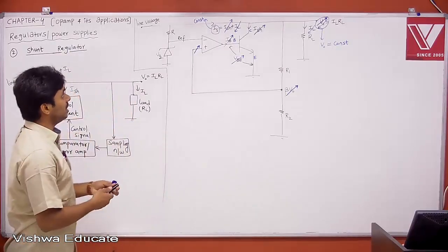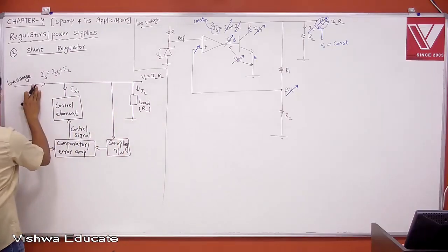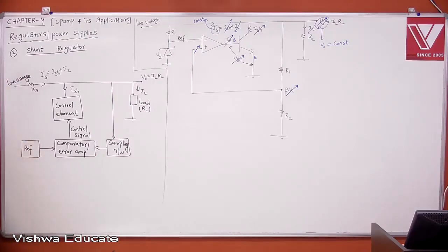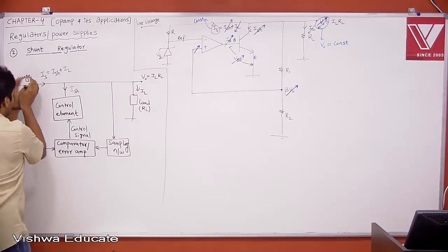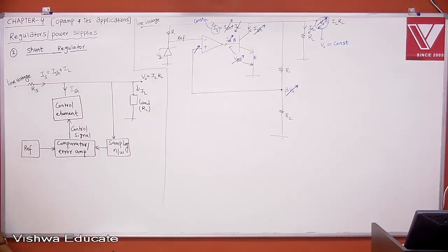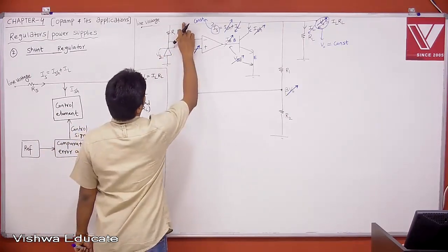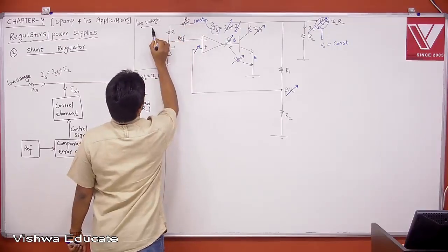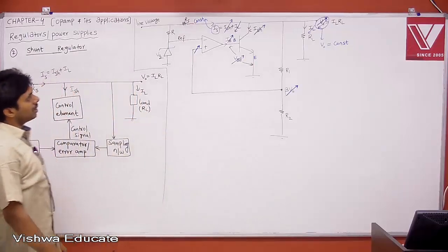The blunder or the correction is, people put a resistor. There should be a series resistor. This is your RS. If the line voltage is increasing, to make output voltage constant, the increase in line voltage will be dropped across RS. The increase in line voltage will be dropped across RS. Therefore, similarly, there should be a series resistor, right? The series resistor, when you keep it, this is our series resistor RS. Okay, now this is correct.